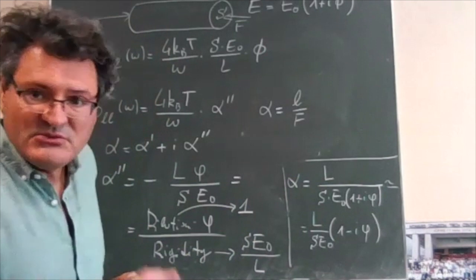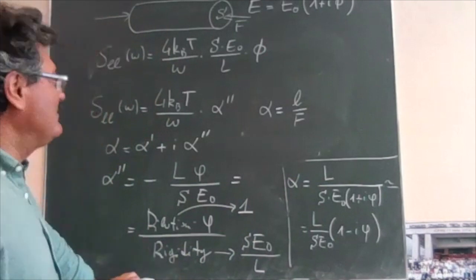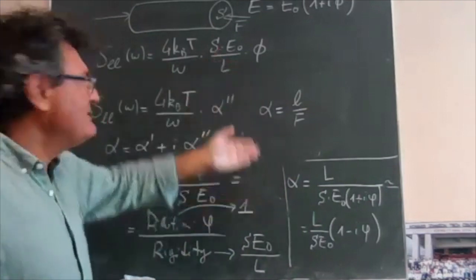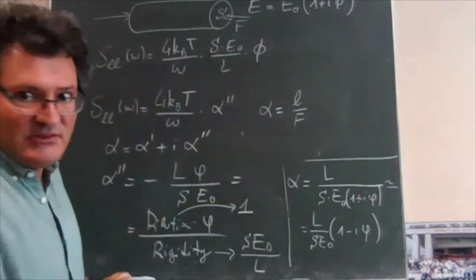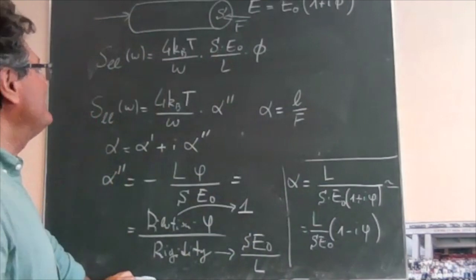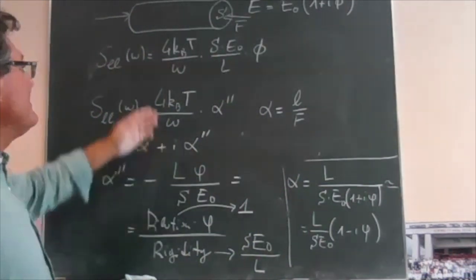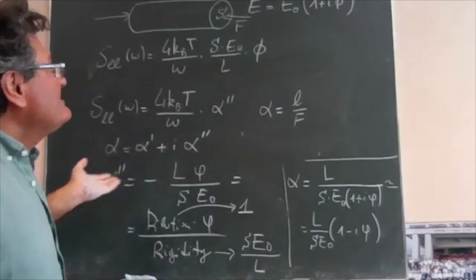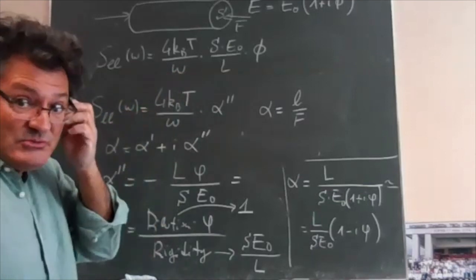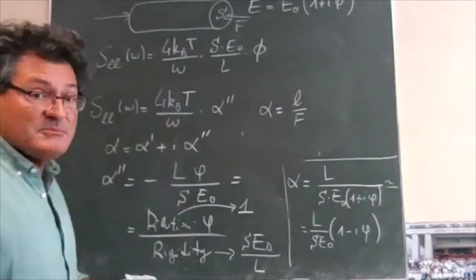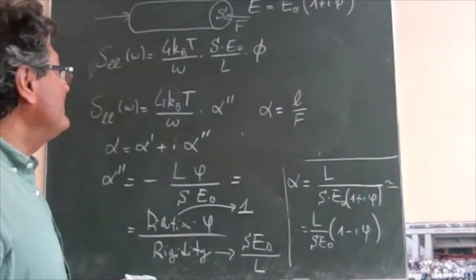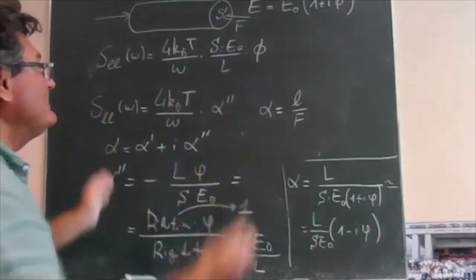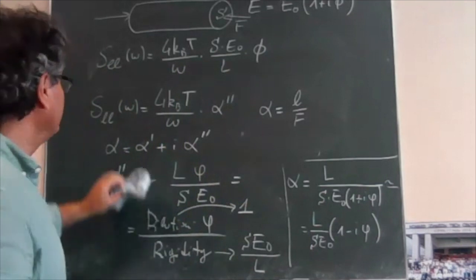So therefore, in order to cut down the problem, we just take phi as positive and with no negative sign on it, okay? So it's not a problem. So therefore, you will see here immediately that you have nothing more to do. This is the expression of the power spectral density of the thermal noise related to the length variation of a cylinder.